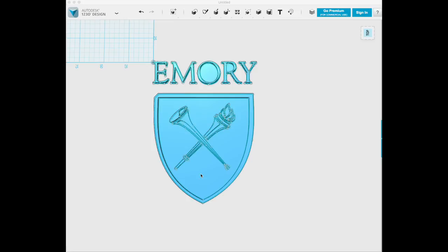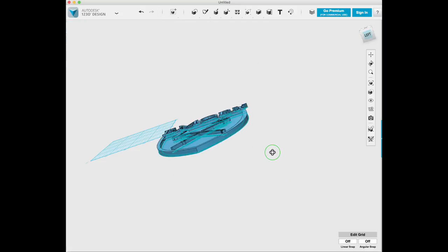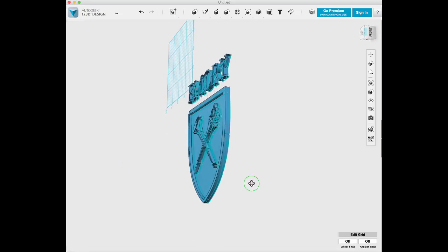It was because it had the art assets there, for lack of a better term, and there was 0 thickness. So if I tried to actually print it, it would break. It wouldn't be a watertight model, or it would have 0 thickness geometry, and it would be broken. So that was a concern. And you can see here, it's all nice and three-dimensional.